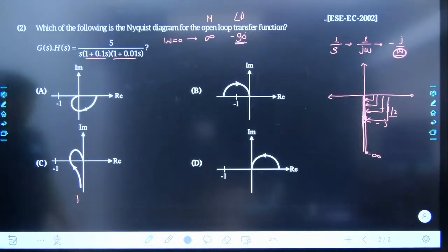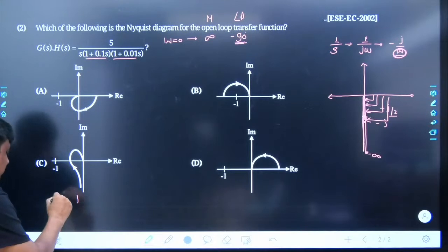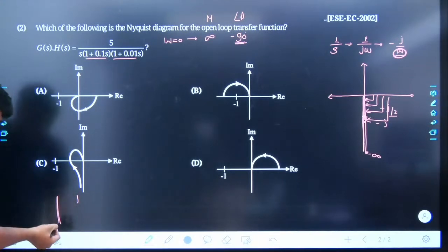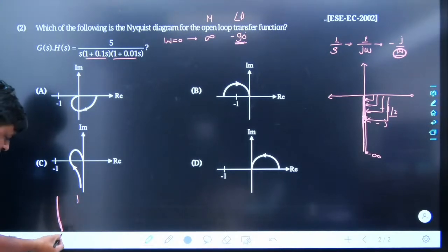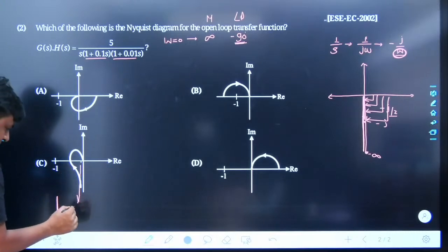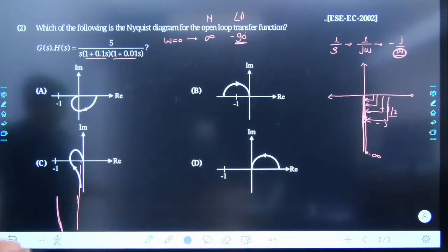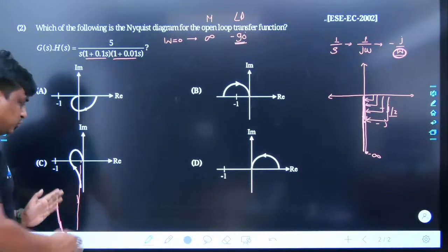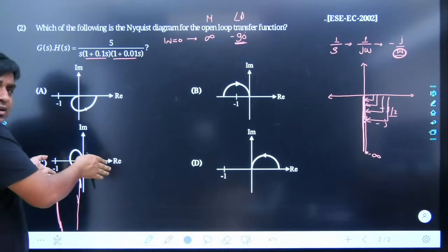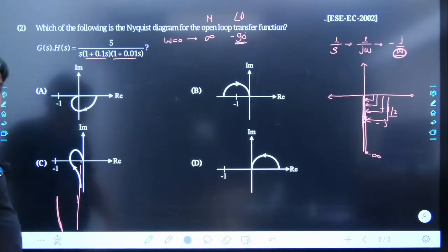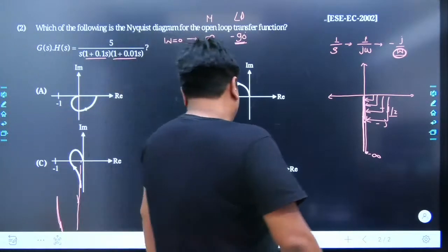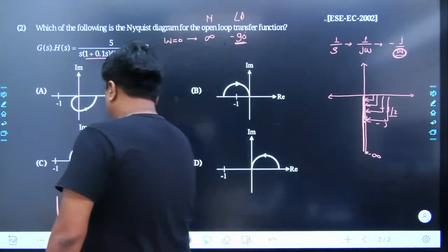No, not necessary. If it has been like this also, if it has been starting from a very, very large distance, still the angle is 90 degree. It is just a representation that we use to stick the given polar plot taking the reference of minus 90 degree, but this is not the case always. Still, whatever is being given, we would accept as it is.